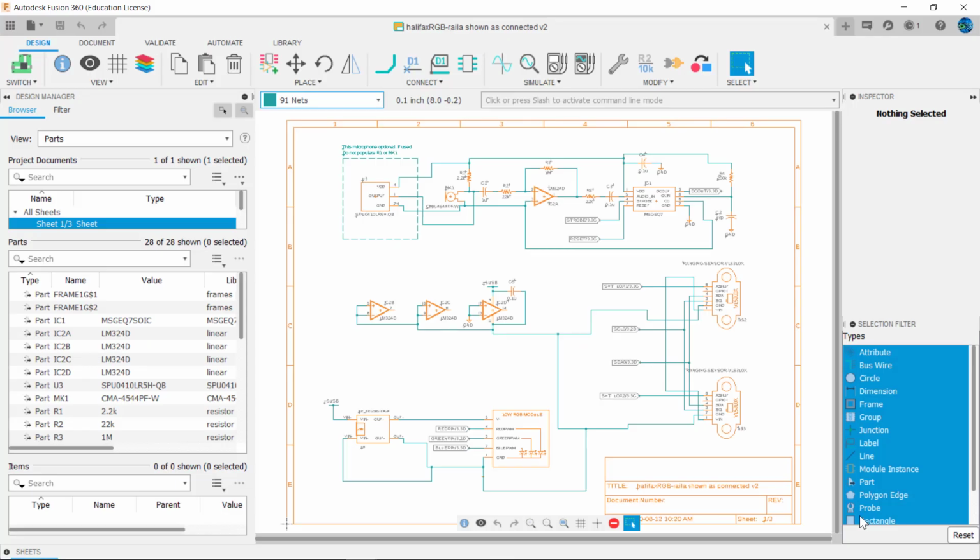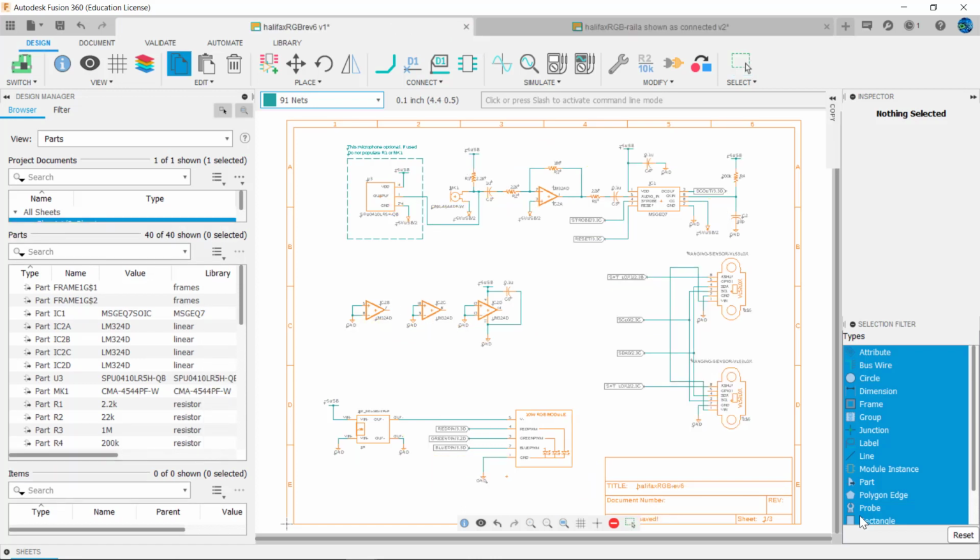Here's an example circuit with power connections to multiple components. I'll highlight them in yellow. Notice how it becomes less cluttered when we use ground symbols and supply rail symbols to represent those connections. Note too that this saves time as we don't have to draw the lines between components to show the connections.